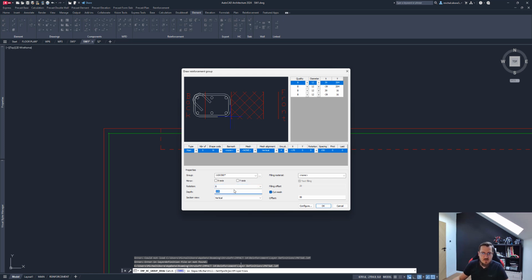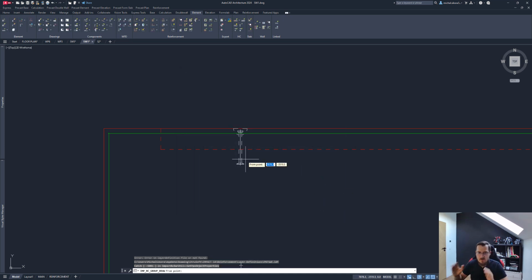Let me now change that offset slightly, so maybe to 20. Yeah, that's too little of a difference. To 35. That was 225, so let's create more of a cover here. If we create more of a cover, that's going to be like, say, 20, 25. Let's go 250. That should be sufficient, and let's accept that. So now I have my group properly horizontally spaced in an element. It's just a matter of now placing it properly vertically.